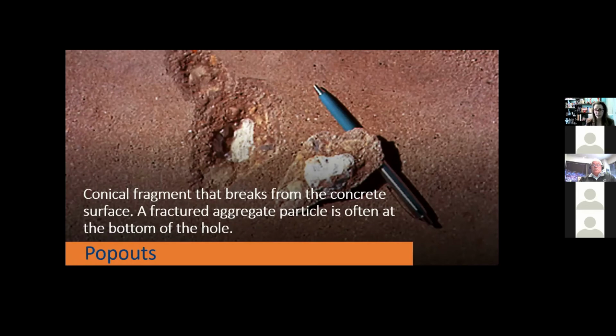This rock here in this picture happens to be chert. It's a low density aggregate with a specific gravity less than 2.4. Is it allowed in concrete? Sure. And I'm not saying that in a negative way. We allow a lot of things in concrete. The specification for aggregates, ASTM C33, allows up to a certain percentage of chert, even in chert free, which is, there's no such thing, but it would be 0.5. To limit these materials is ideal. And of course, I didn't want chert in my driveway, but I walk down our streets and I see it everywhere.